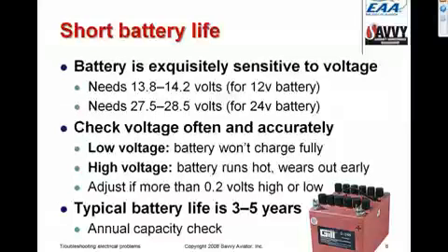And what's most likely wrong is that the system bus voltage is not properly adjusted. Batteries, unlike almost everything else in our airplanes, are exquisitely sensitive to bus voltage.